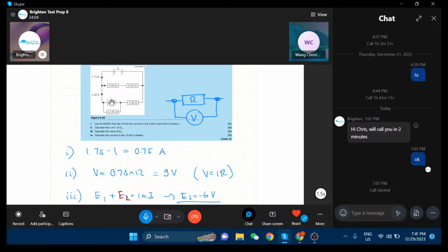So now the current here is really only dependent on exactly these two: I have the 12 resistance because I have the resistor here, and I have the potential difference from the E2, the 6 volt. There can't be anything else. Why? Because when you look at it, they are parallel, right? So in the parallel circuit, you must have the same voltage here.